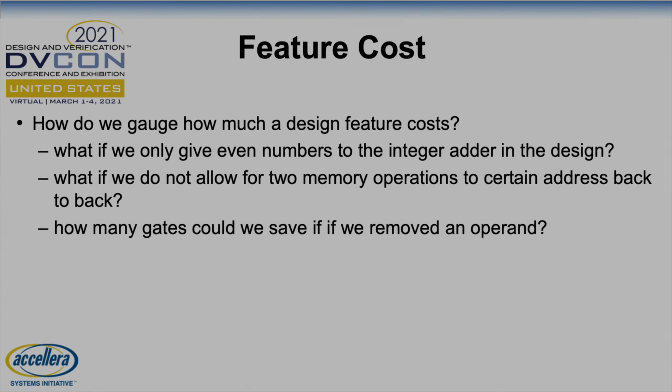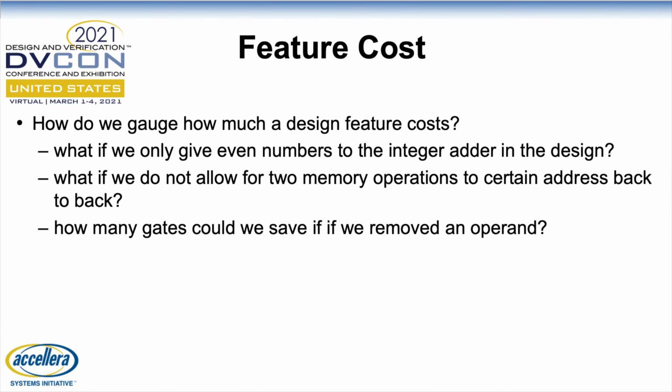When we talk about realizing a design in gates, we have to realize that every single feature, every ability that logic has, has a feature cost. And that cost is sometimes very hard to quantify. The only way you could do it now is with all those designers, parameters, and defines, and allowing the synthesis engine to use that smaller logic to realize the design.